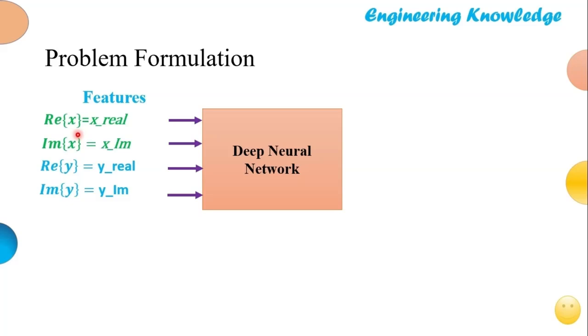So basically now we have four features, because x, the QPSK, is complex, and y is going to be complex. I'm trying to simplify this, so I'm taking h to be a simple thing. The fading coefficients will be simple. I will assume a Nakagami-m distribution in this demonstration. So after training we estimate h, and that happens to be h hat.